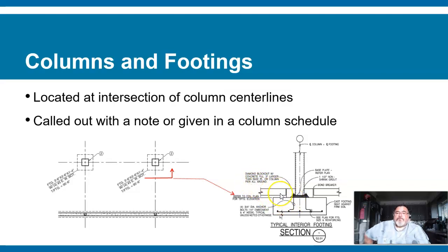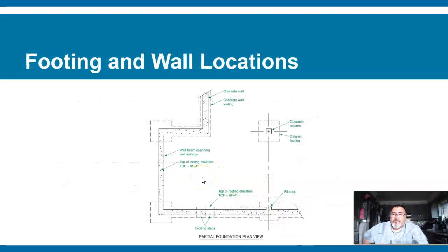So this is like a floor that gets poured over the steel bolt later. And then because you have a base plate, it gets bolted down. It's on top of some type of grout that helps level it. And then you have this bond breaker, this little space. It's like you pour the footing and then you pour this little separate section. So we looked at a column, we looked at the footings.